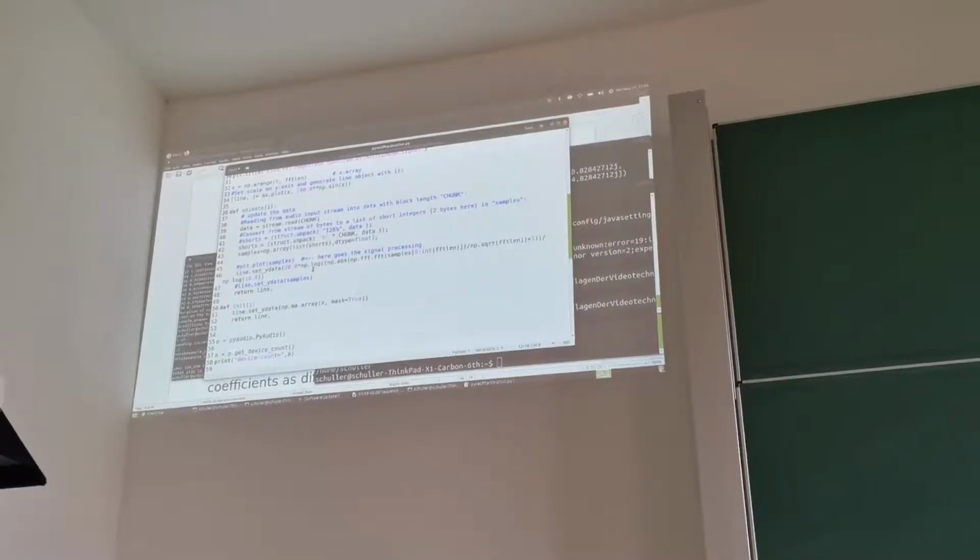And so this is the dB value for voltage. And we assume that we get voltages from the sound card. Again here, normalization to make this log a log of base 10. So log in general is a log of base e. And you turn a log of base e into base 10 by dividing this log by the log of 10. So this is kind of a trick to get a different base.